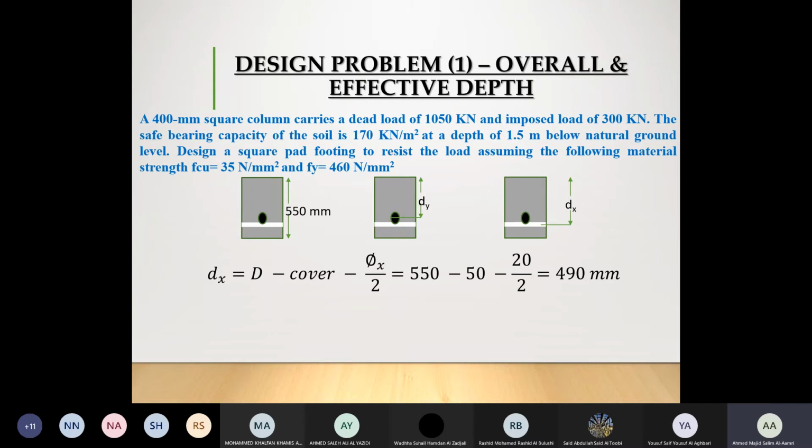Loading is higher, loading will cause bending to be higher, bending will cause the area of reinforcement to be higher. If the area of reinforcement is higher, then of course you will be having a higher bar. The smaller bar is not going to be sufficient. Okay, so normally we start the foundation from 12 mm. Normally for the slab you started from 10. For the foundation normally we start at 12 or 14. Now in this problem I have assumed my reinforcement to be 20 mm.